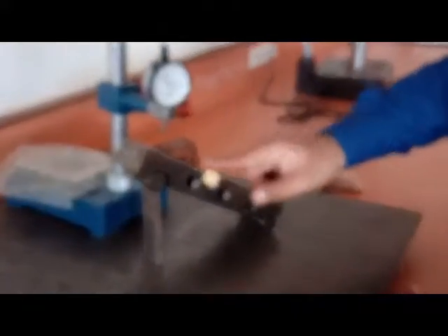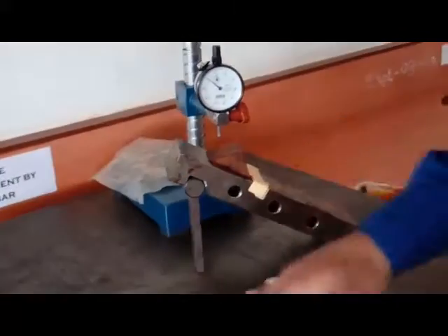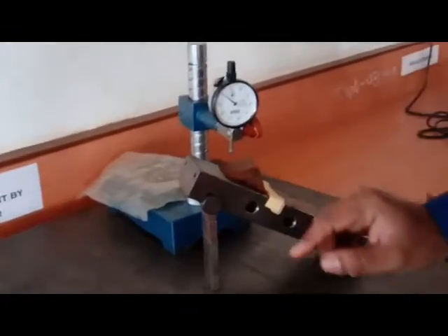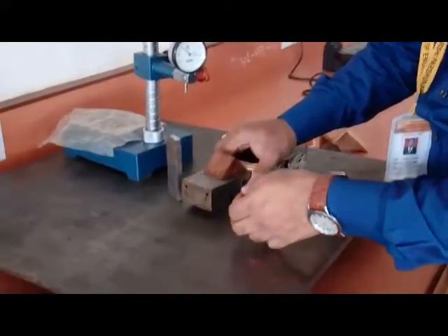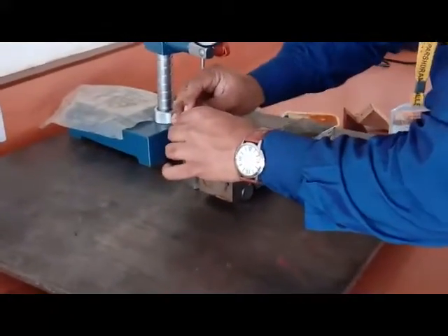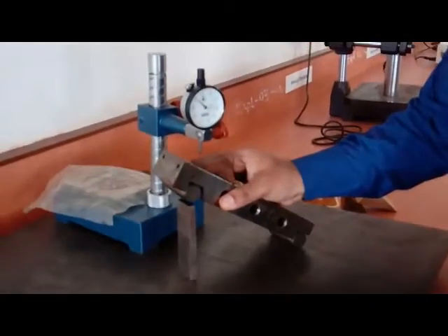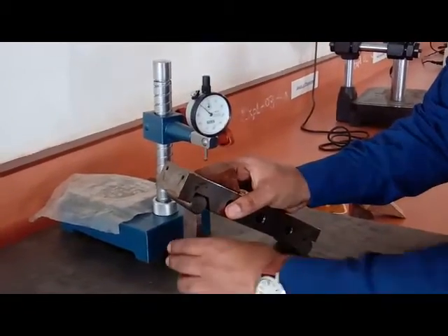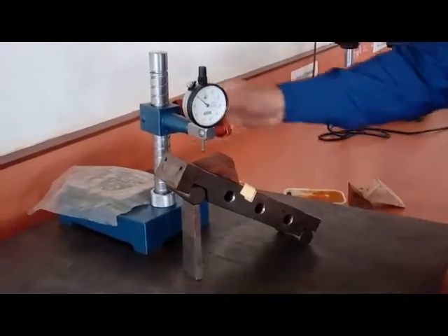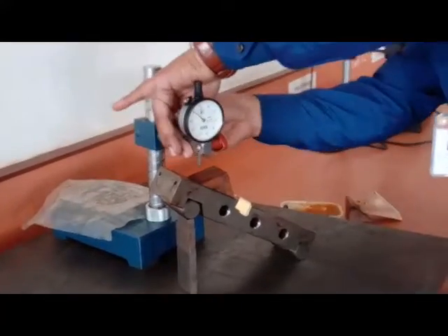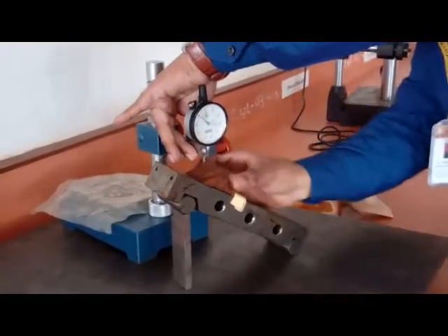Then if you can see, the taper angle is now shifted to a parallel angle with the surface plate, but still it requires a smaller adjustment. We will take another slip gauge of 0.4 mm, and we will connect it in a similar manner. After this you can see the component is properly parallel. We will adjust the dial indicator and check on the different surfaces.